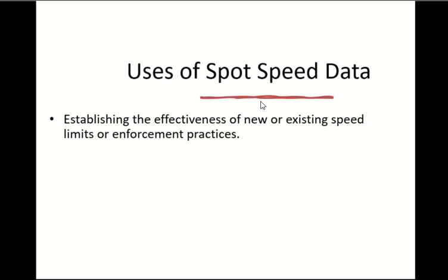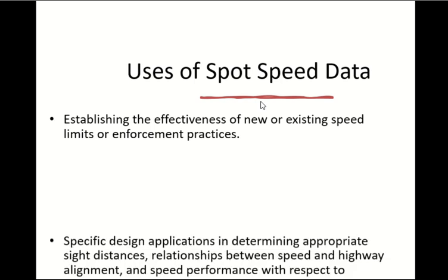What is it? A waste of money, right? And then you go to a small street and put a speed limit of 100. What are you trying to do? Kill people. Right? It does not go according to the expectation of the driver in that situation. So the speed limit should follow the expectation of the driver. This is the first thing here.